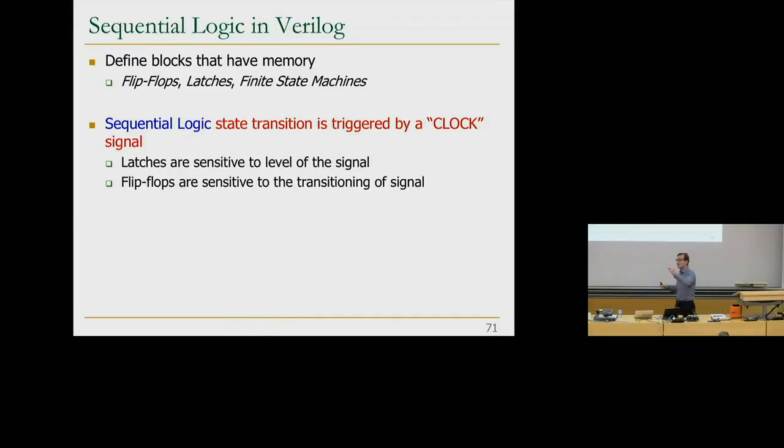If the signal is 1, then the latches will latch the value transparently. If the input changes while the signal is 1, you will see the output in the latch. That's why they're transparent. You'll see the output reflecting the input.